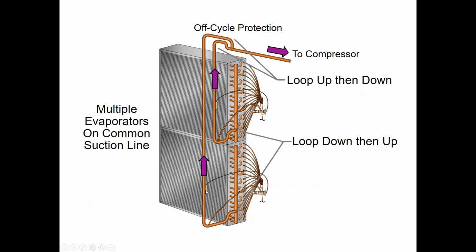You want to have it somewhere near the sensing bulb, a little bit before the sensing bulb, but in the same area. Okay. The mounting of the sensing bulb while we're looking at these headers is something to think about as well. The sensing bulb, in this case, in the vertical position, on the vertical section of pipe, the sensing bulb itself has a right side up, upside down mounting, right?